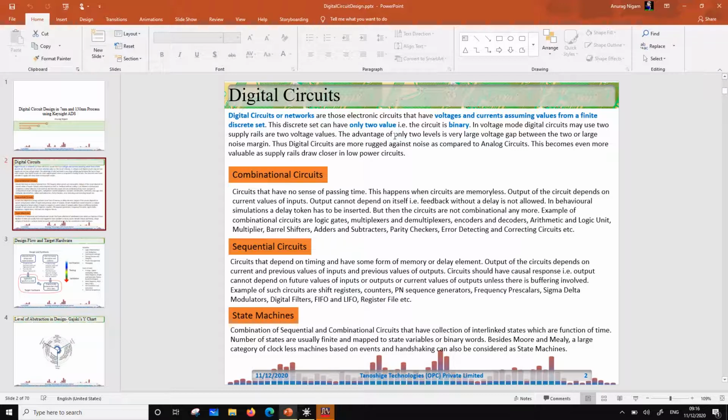Or it can be the shift registers, which are made out of the registers themselves, so that you can shift the bits to the left or the right. They can be ring oscillator kind of circuits. Rather, I would say not ring oscillator. You can circulate the bit within a register, right? So such circuits are there. Then you can have these shift registers with feedback. They are usually known in the literature as PN sequence generators.